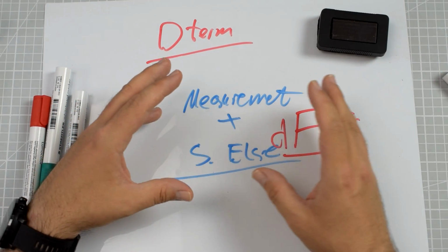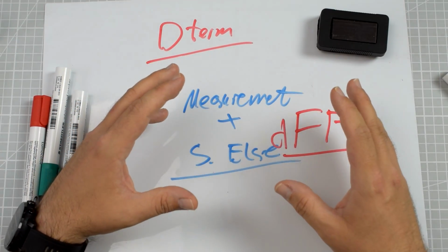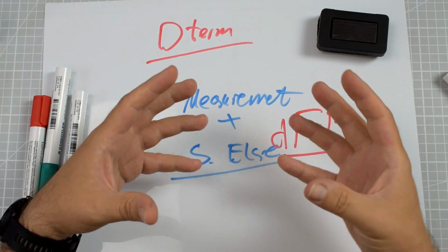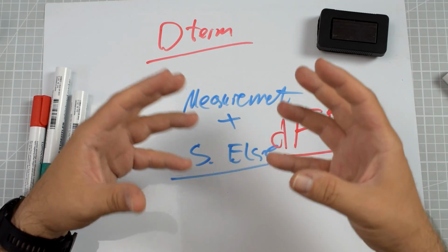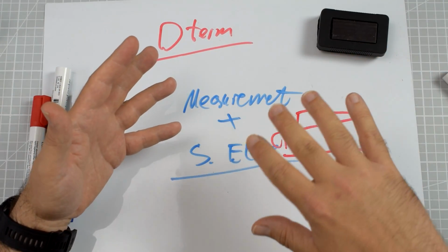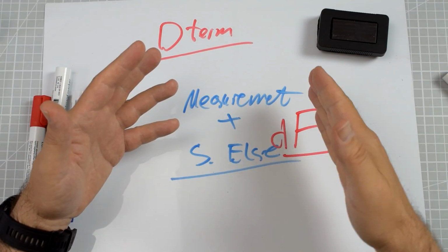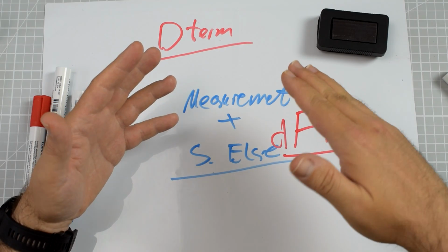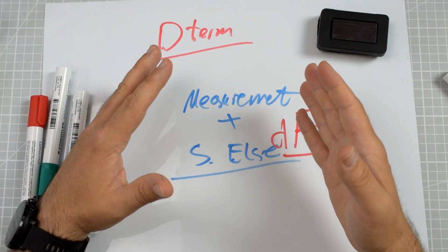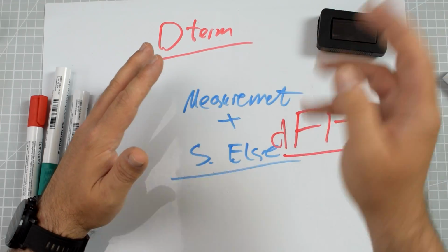This is why the D-term itself is handling only the smoothness, the softness of the response of the actual flight, so that, for example, the end of the maneuver is not very rapid, but rather with a slow deceleration at the end, and also the acceleration is not very rapid but slowly starting.